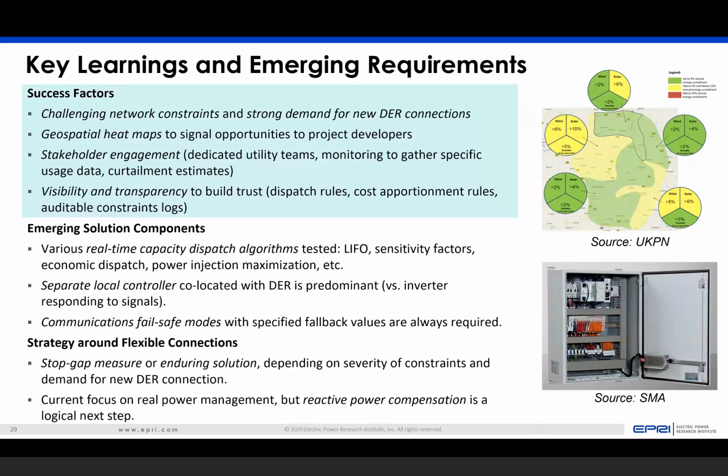In terms of solution components, it's important to work with regulatory bodies to agree on what the predetermined dispatch algorithms are, which dictate how curtailment will occur and what the rules are. This is particularly important for more complex arrangements involving multiple DERs contributing to perhaps multiple constraints on the system, where the rules governing who gets curtailed when can really change project economics.